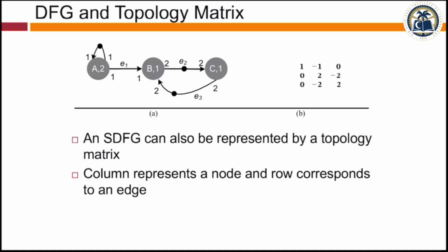Wherever you see a dot here, it means it is storing a value. So this node will be requiring the previous value. So it's a register, a physical register. If you don't see this, the same value goes here. But if I put a dot here, it means it is not the value which it has just generated, rather it is the previous value which was generated. Like in the filtering process, we have something like this.